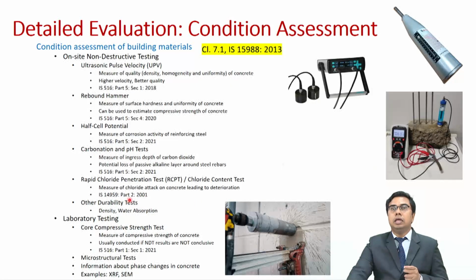Now, if your non-destructive testing provides you a result which is believable, what I mean by believable is that if you conduct UPV and rebound hammer at the same location and both of them give you good values, then you can rely on that value.